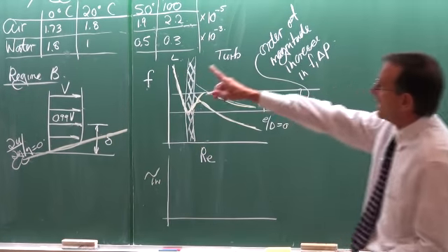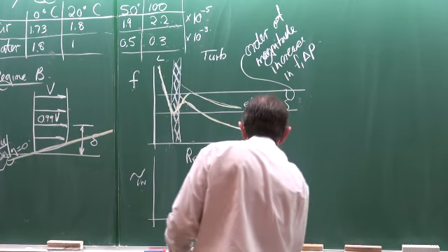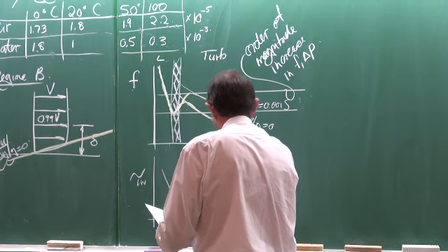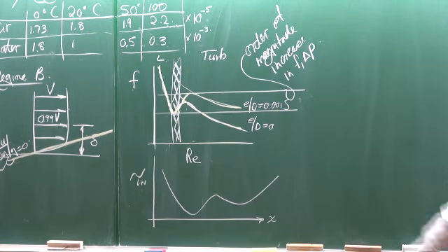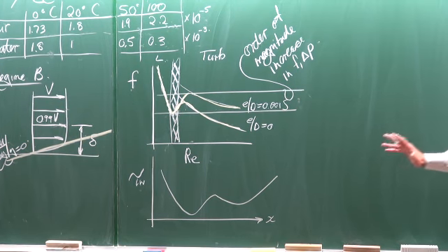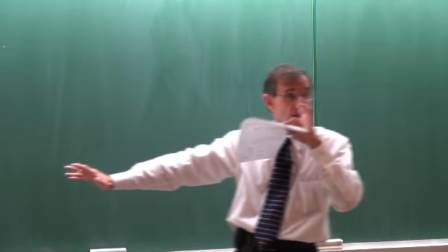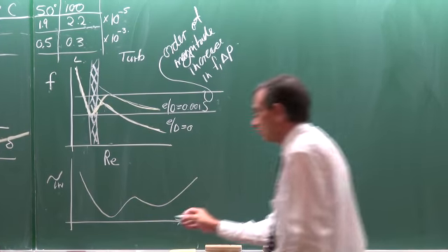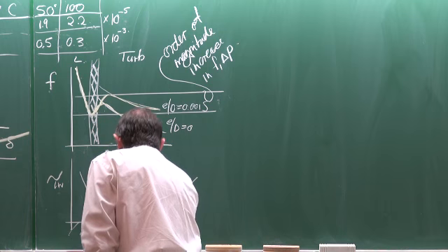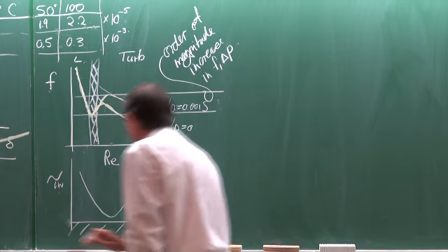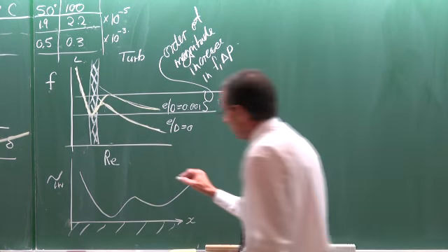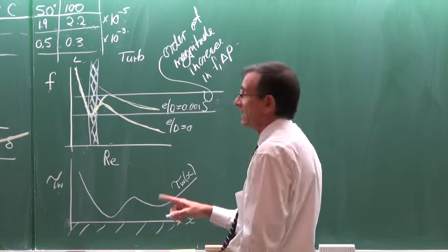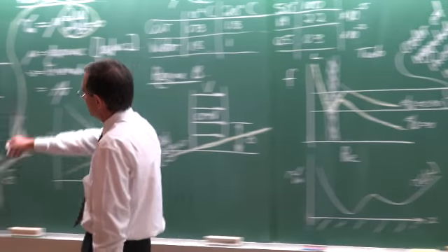So on a flat plate, there are similarities with a tube. If you look at that wall shear stress as a function of x, then it actually looks something like that. The reasons we are not going to discuss now. It has been done in fluid mechanics, and as you can see, that is what is going to happen on a flat plate. So what we can also see is that the shear stress is a function of x. Does it make sense?